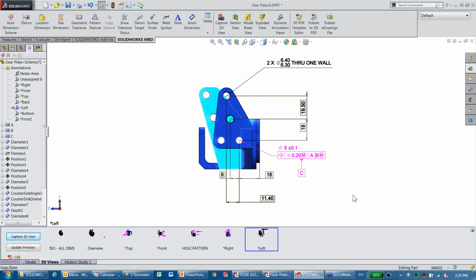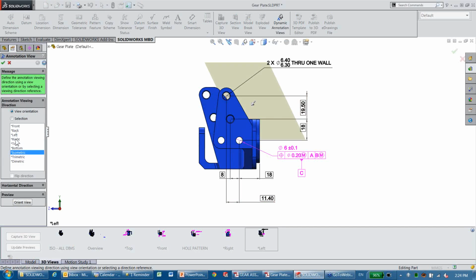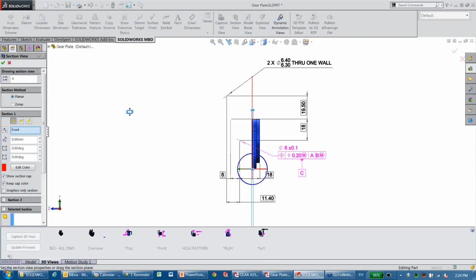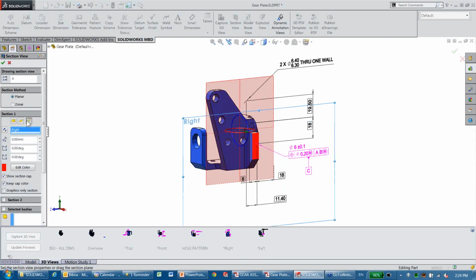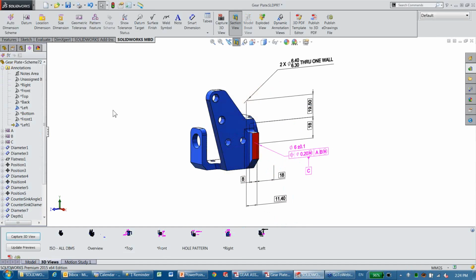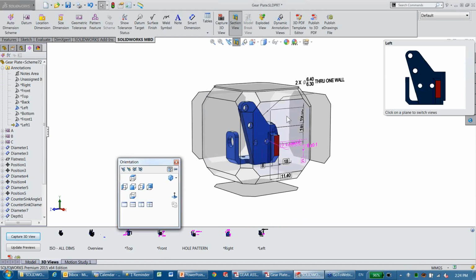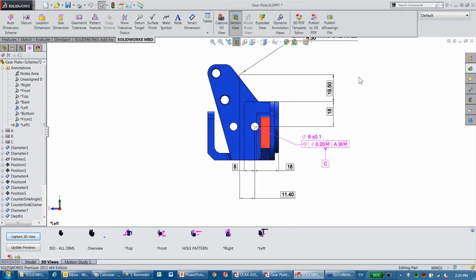You would call out a section view and go detail on the second face and hide part of the model. Well, we're going to do the exact same thing here. So first of all, let's create an annotation view, and I'm going to call it from the same orientation I'm working on right now. And I'm going to simply start a section view, set the right orientation. This is better. So I've got my section view going. Let's just reorient our model so we can see it from here.